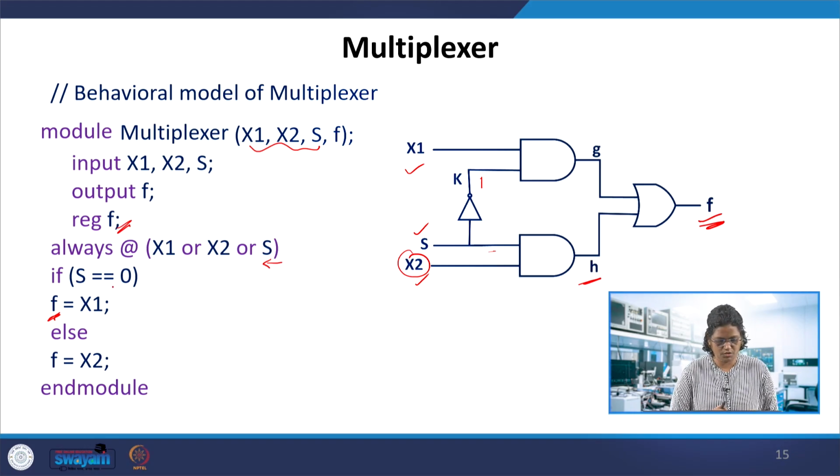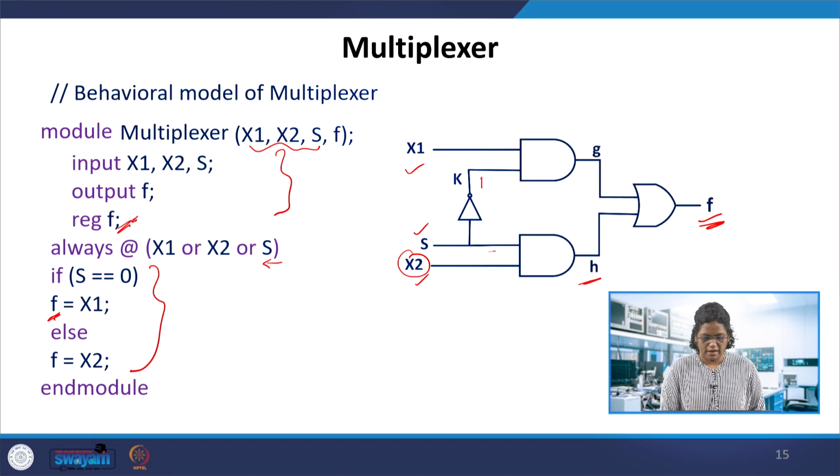Now what about the wire declaration, how does it work here? The wire declaration doesn't come in the case of the behavioral description. So you can have this very simplified code describing the functionality, the behavior of the circuit. It's a behavioral description, or procedural code, like in any other language. The reg declaration in the declaration part is the only add-on compared to the other types.